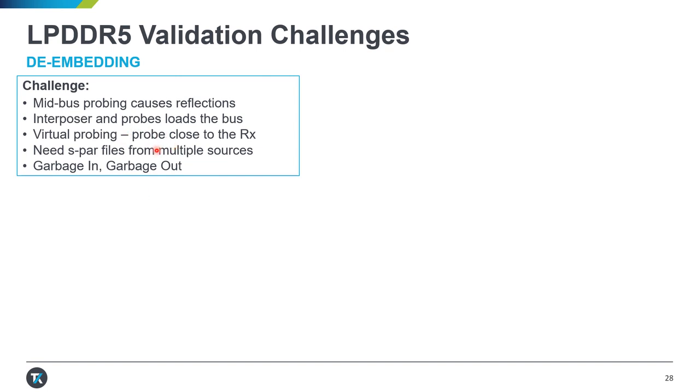Now, in order to correctly apply de-embedding for both read and write cases, we need to faithfully represent the channel. One of the ways this can be done is by using S-parameter models of SoC package, DRAM package, boards, interposers, and probes. We also need to know the TX drive strength and RX ODT termination values. So conceptually, de-embedding is very simple, but implementing it correctly is not that easy.